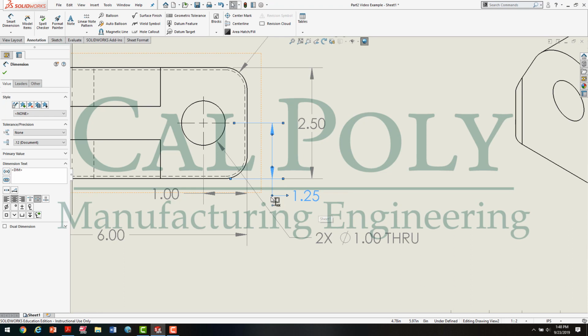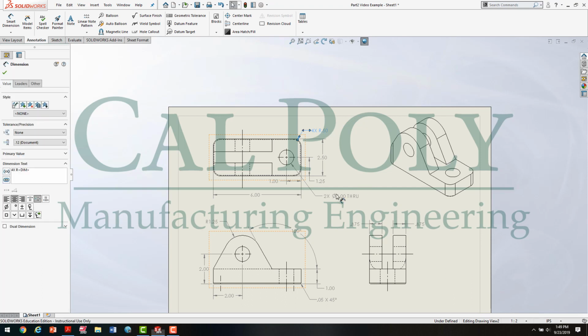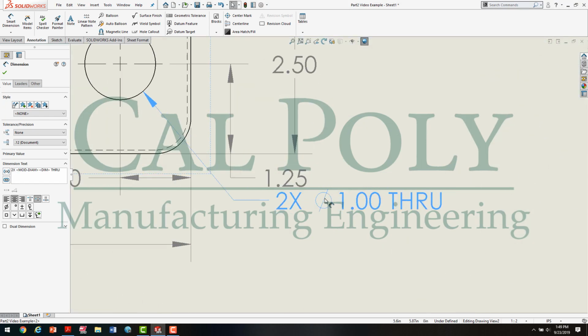If I wanted to flip it to the other side, you could click on the little dot right here, and it goes back and forth. So wherever you basically move it, it'll follow with you using the ANSI or ASME Y14.5 standards. So moving this in, you want to clean up your drawing, make sure there's not a lot of confusion with cluttered dimensions.